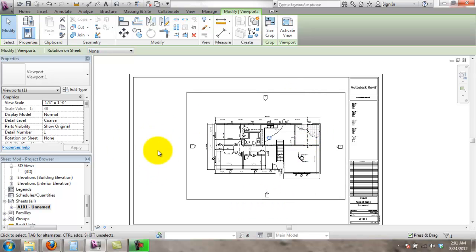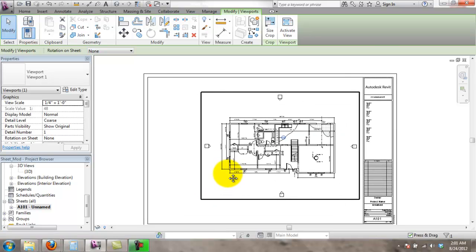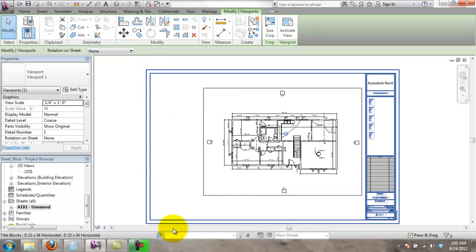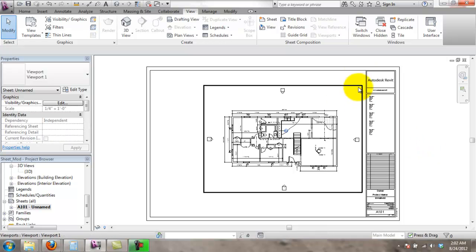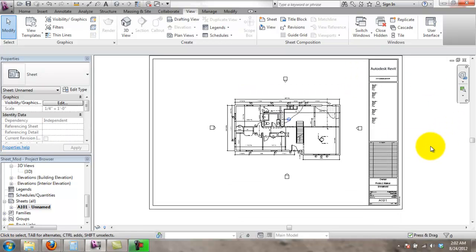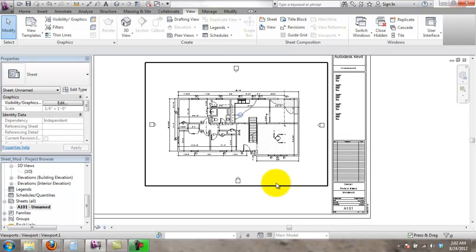You want to limit what you put over here, because when you have a bigger project, you're going to bind these sheets, and if you bind things on the left, whatever is in this crease, you're not going to be able to see. So whenever you put things on sheets, make sure you put them all the way over to the right. All right, so we're going to keep everything else on here. This is all we're going to put on this sheet.